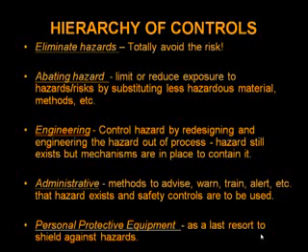Can we abate the hazard? Can we then limit or reduce the exposure to it by substituting a less hazardous material, as we might with chemicals, change our methodology, or reconstruct the task itself? Can we engineer the risk and the associated hazards out of the process, the job itself, and control the hazard by redesigning the operation? The hazards may still exist, but we've got controls in place that may help contain them.